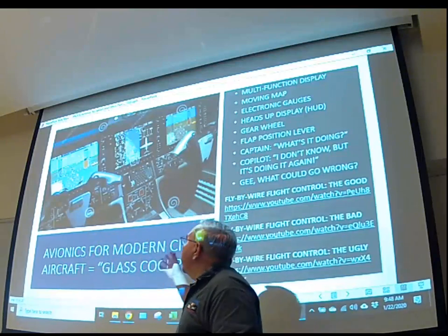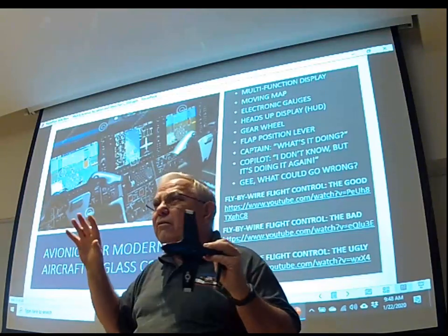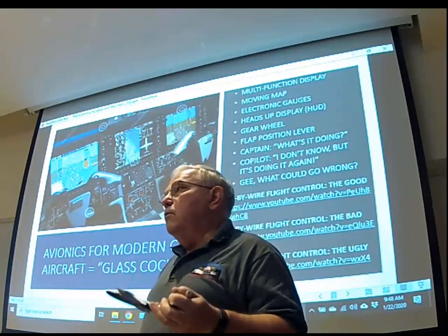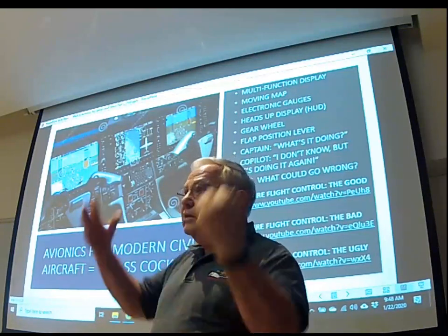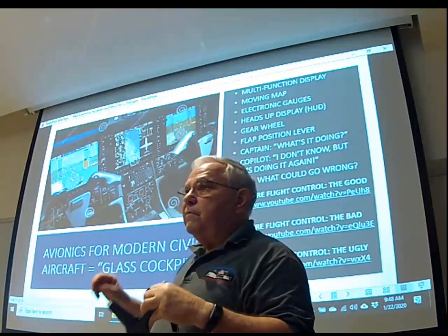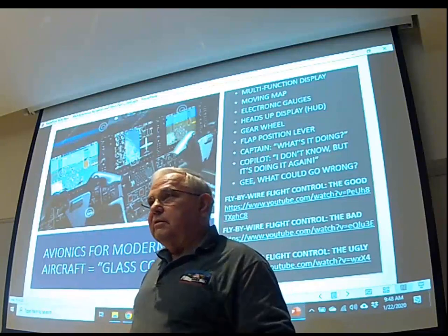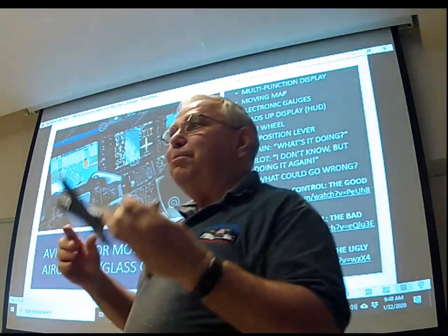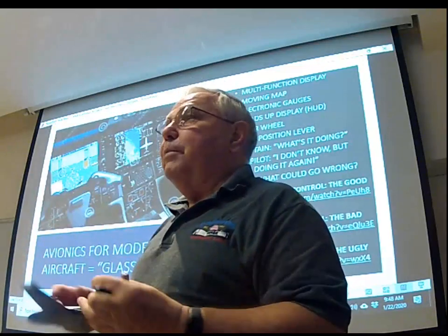So you see the pilot gets behind the aircraft, and the aircraft, if they're unstable like most fighters, or even the airliners are very close to unstable, they'll take off on their own. They'll just fly the way an airplane is going to fly, which is not always good in modern times. So they crash. So you have to be very careful. It takes a lot of knowledge of the systems, training, and awareness of pilot lag. Watching these examples, that's a Nova show we watched that said the system will never let you do anything wrong or bad. Yes, it will. You can deplete the hydraulic pressure under certain circumstances, or if something depletes your hydraulic pressure, then you better have a backup plan.